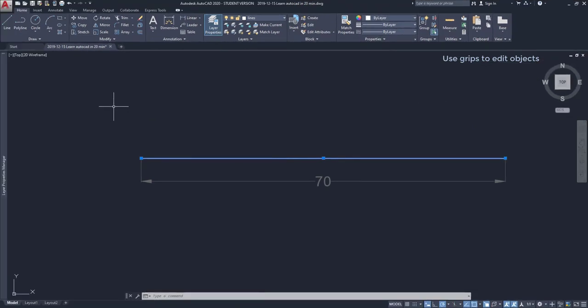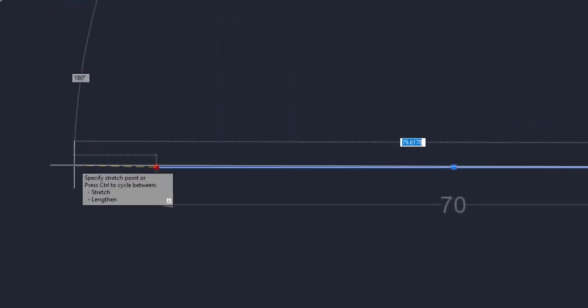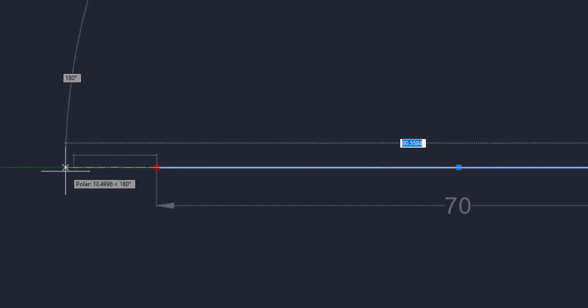To type a new length for the line, I click on the grip, drag left and this time I press the button Tab and the input switches to the full length. I am going to insert 120.